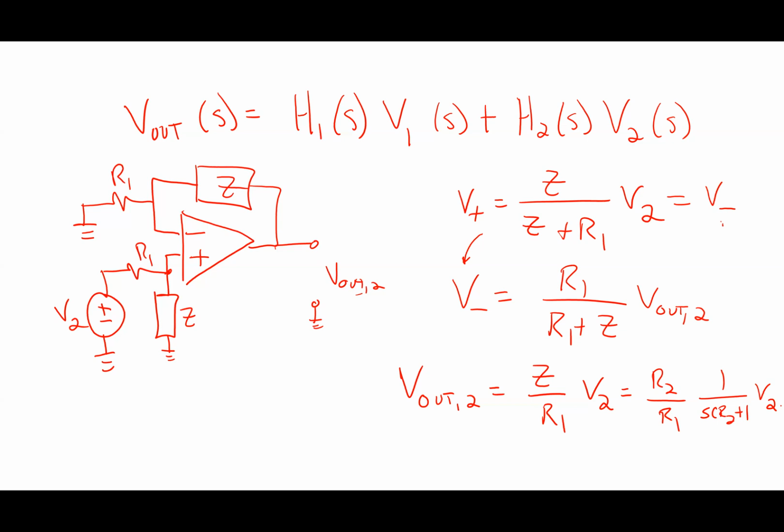Questions about that? Like, if I do the multiplier, does that mean the R is 4, or if R is 2, then what? The multiplier is just the math thing. When I look at that transfer function, I got a constant, R2 over R1, times 1 over S tau plus 1. So the constant on the whole thing is whatever the K value is. In this case, R2 over R1 is 5, I think is what it works out to in this particular example.